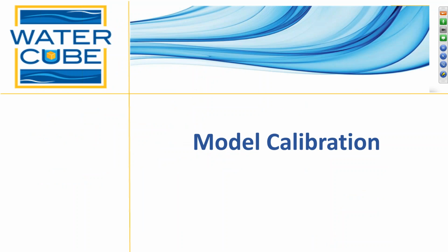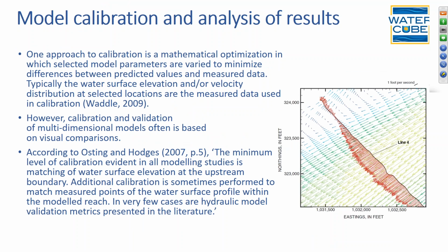And then I want to talk just a little bit about model calibration. And I've shown this figure before, and again, this is a different cross-section line, the same report, but once again, very dense data laterally, very sparse longitudinally, versus our model values, which we have everywhere. And in general, what we do in our modeling is we'll take a figure like this and say, look, you can see we've done a pretty good job. My directions are right. The high magnitudes here match the model. We've got the low magnitudes and the reverse flows. So in general, we've done a really good calibration here.